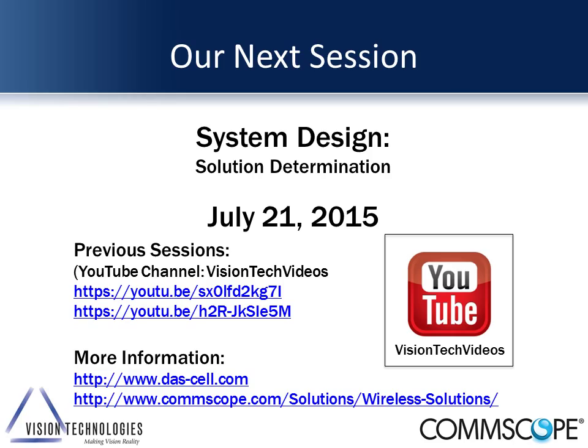As an OEM, we really like LEED buildings because they have special treated low-E glass windows. The good news is these low-E glass windows keep the environmentals working more efficiently in terms of heating and cooling. The bad news is if there's a cell site across the street, the signal will not penetrate the building. So if it's a LEED building, you can pretty much be guaranteed that they're going to need some kind of help.